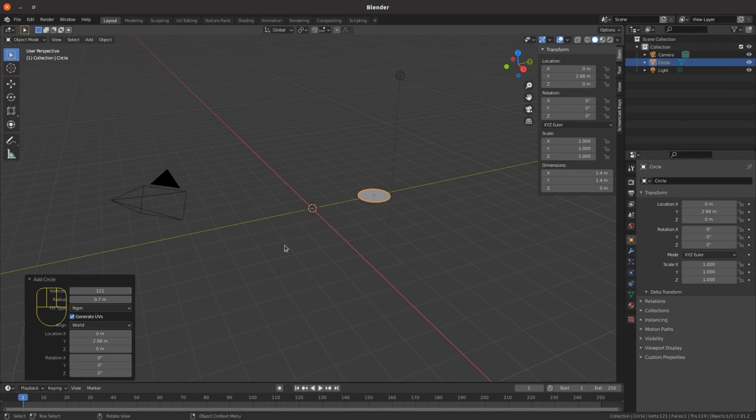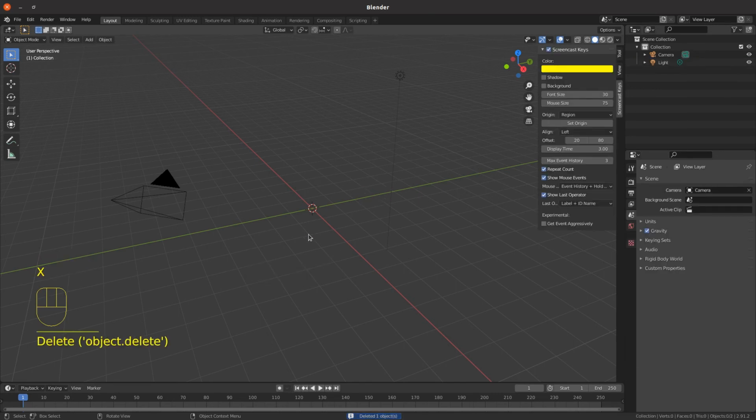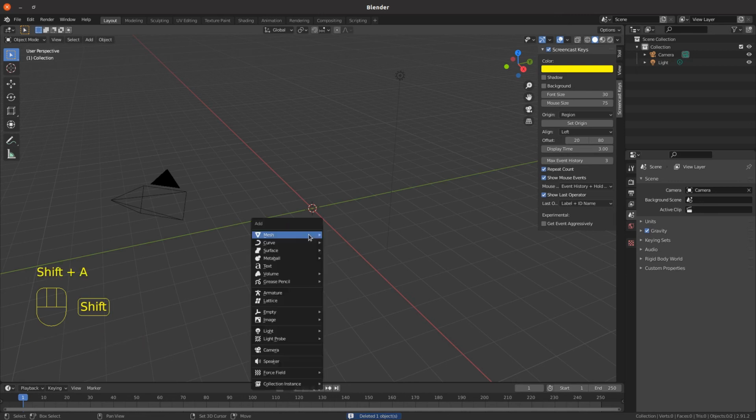And again, once you come out of that, you lose the options to change it, and then you can edit it, or you can use the move command to move it, scale command to scale it, and go into edit mode and completely change its shape. I'll just delete that with the X. Oh, sorry, it's not selected at the moment. X, delete. And some of the others, Control add.